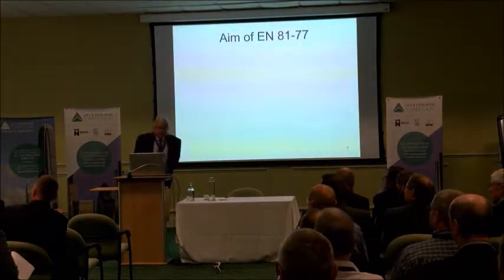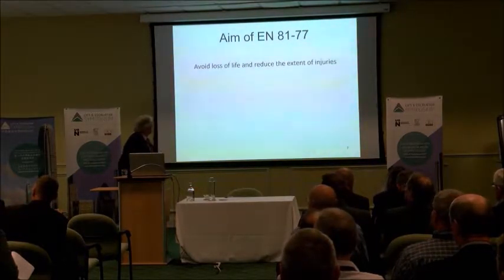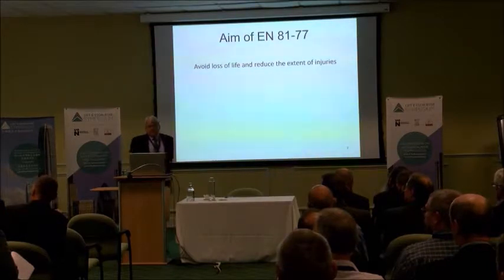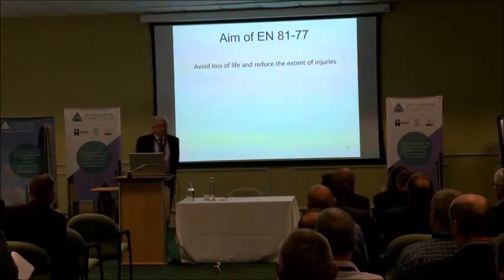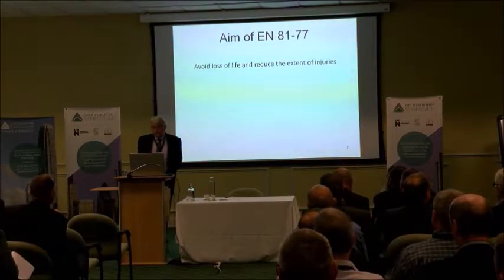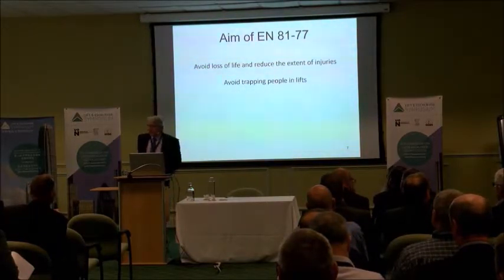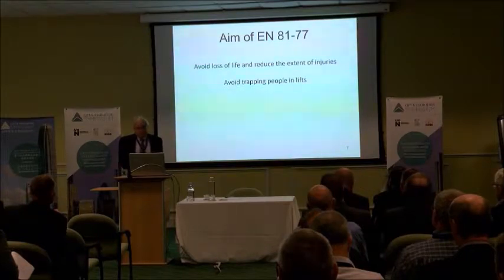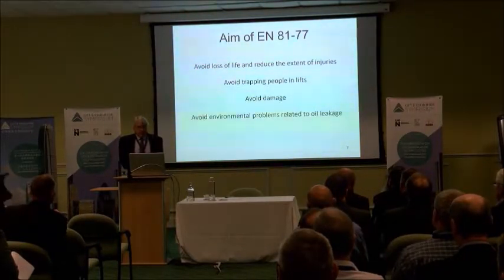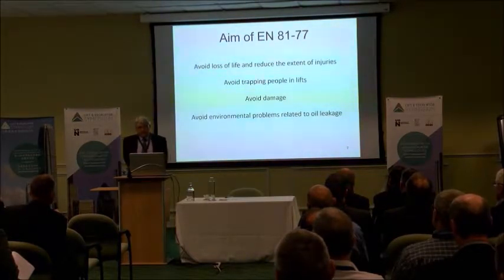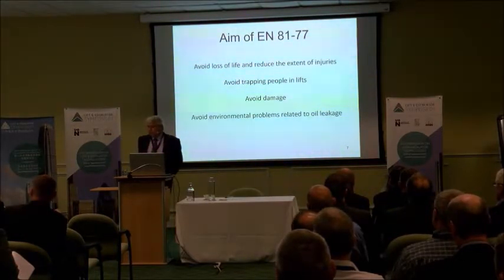Talking about EN 81, the aim of EN 81 is to avoid the loss of life and reduce the extent of injuries associated with lifts during seismic conditions, earthquakes. We want to avoid trapping people in the lifts, obviously, and we want to avoid damage in general, and we want to avoid environmental problems related to oil leakage with hydraulic elevators.